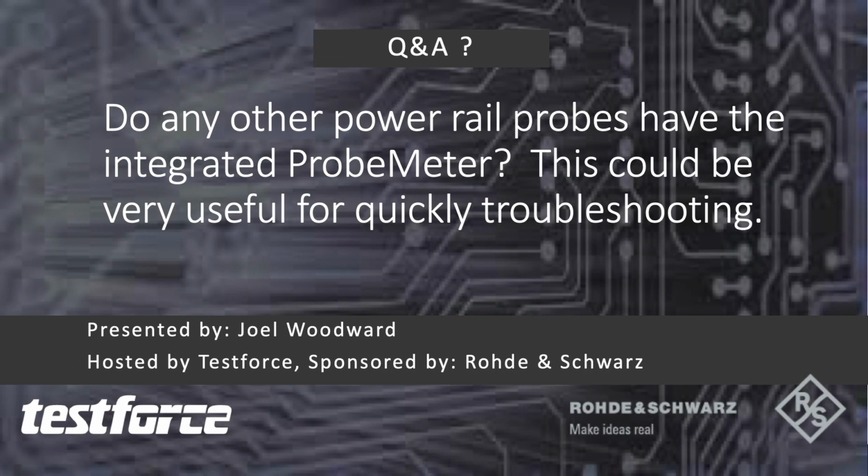Do any other power rail probes have the integrated probe meter? This could be very useful for quickly troubleshooting. So the Rohde Schwarz power rail probes, as stated in the webinar, have an additional ADC. It's an 18-bit ADC integrated in the probe itself. It digitizes the DC value of the power rail probe, sends that back to the scope, and it's 10 times more accurate for DC measurements than a traditional analog scope input is. I am not aware of any other power rail probes in the market that have that capability.